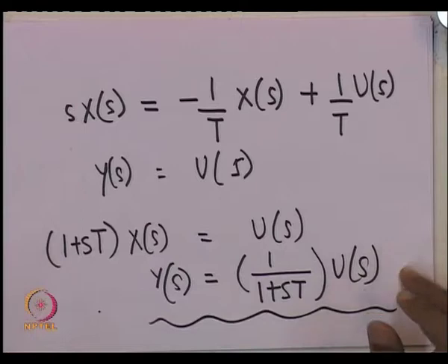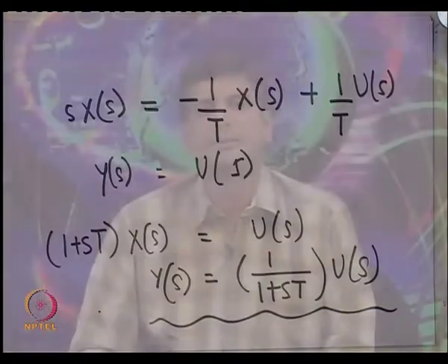In fact, input output relationships have been discussed in the past. When we talked about the modeling of a synchronous machine, when we actually correlated what we get from measurements, the frequency response obtained from measurements, we did use a transfer function representation of the synchronous machine. Therein also, the basic differential equation model of the synchronous machine was reduced to an input output relationship by using this Laplace transform variable s. Okay. So, remember that 1 upon 1 plus sT represents this transfer function.